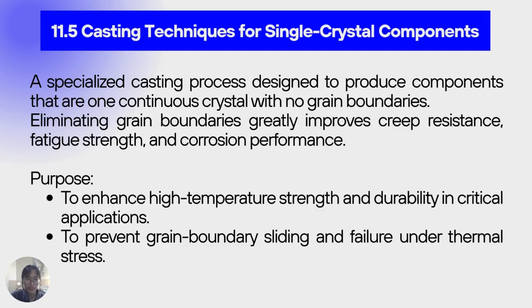Casting techniques for single crystal components are designed to produce parts made of one continuous crystal structure with no grain boundaries. Eliminating grain boundaries significantly improves high temperature strength, fatigue resistance, and creep performance, which is critical for components exposed to extreme heat and stress.